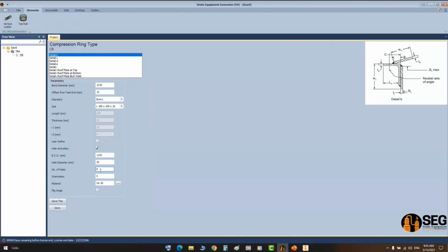They make the roof blade with a flange at the end, and they make it bolted because they have small diameter tanks, and they design it to be bolted at the top. So we create this option for them to make the top angle with an option to tighten another flange with it, or another blade with a hole.